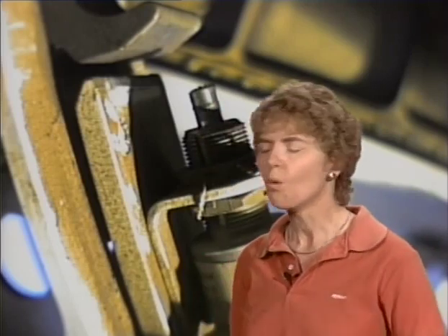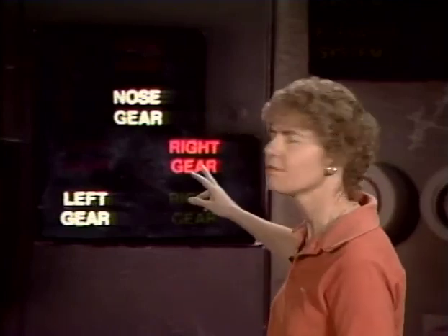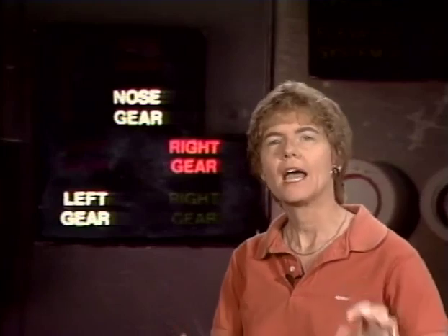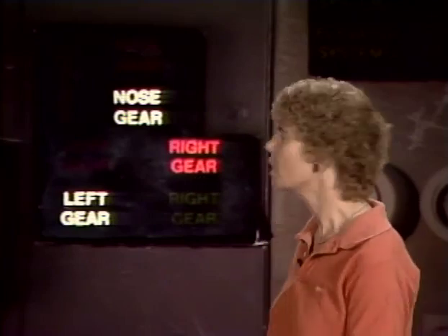Now, when you've got an aircraft with retractable landing gear, you're going to have some landing gear warning devices. What do those warning devices provide? Well, the landing gear warning devices will usually provide some lights, a red warning light, for instance, for an unsafe gear condition, a green light for gear down, and no lights at all for gear up. And in addition to that, there will usually be a horn or other aural device that tells you if you've got an unsafe gear condition. So the red warning light is if the gear is not safe, it's not down and locked, or it's not up and locked. A green light if the gear is down, and no lights at all if the gear is up.